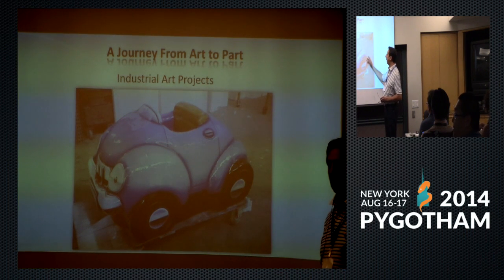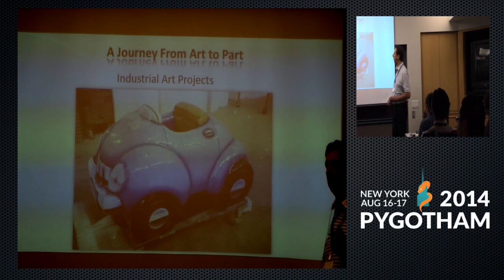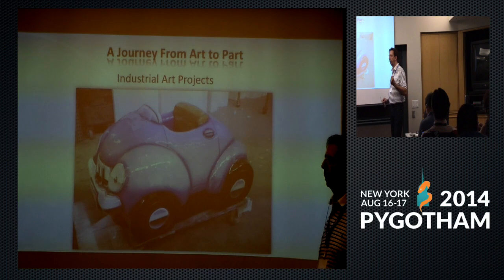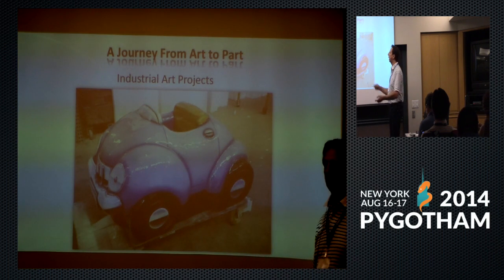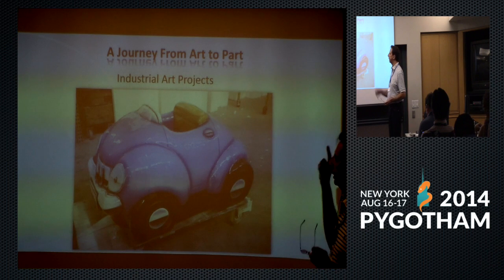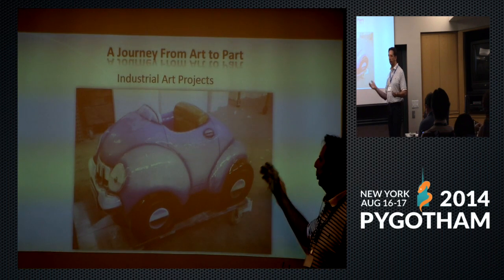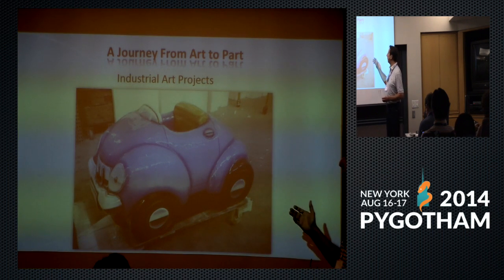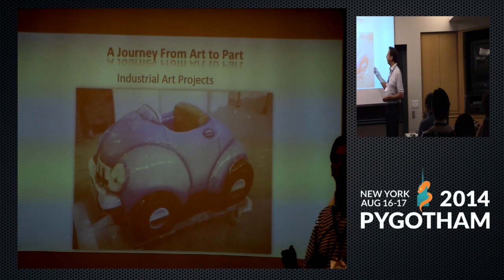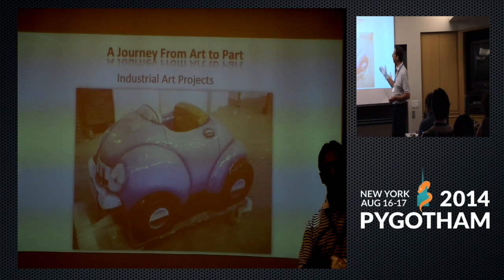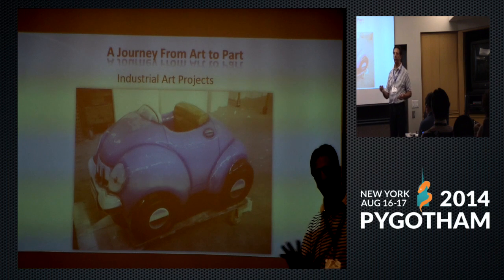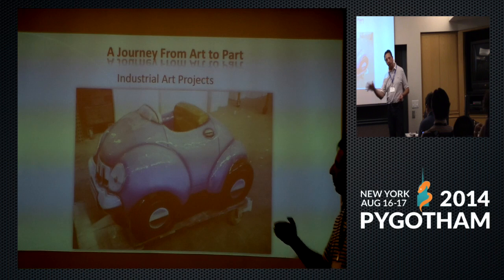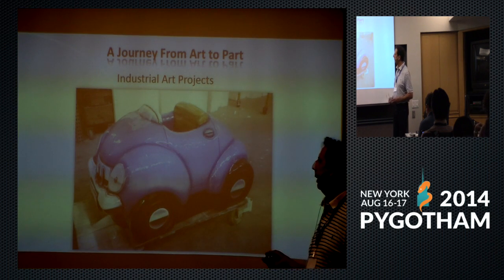So then what we do is we sand this roughly, and we upholster it with an EVA foam, which is like neoprene, to make it soft for kids. So if somebody runs towards a car chasing somebody else and he stumbles and falls against it, it's only a boink and not a crash and ambulances and 911, so that doesn't happen. Then we put a layer of a sprayable rubber on top of the EVA because this neoprene is not very durable. You could take your fingernails and take that foam apart. So we put a harder rubber on top, which is then airbrushed and clear coated.